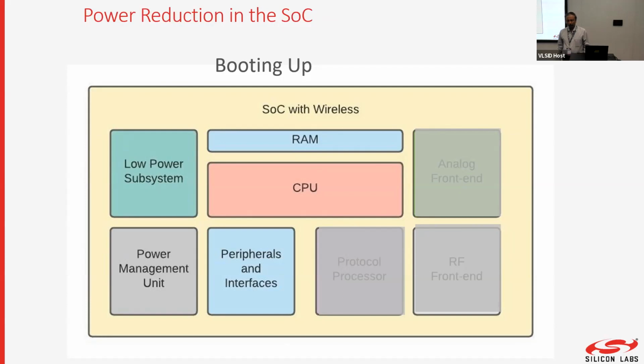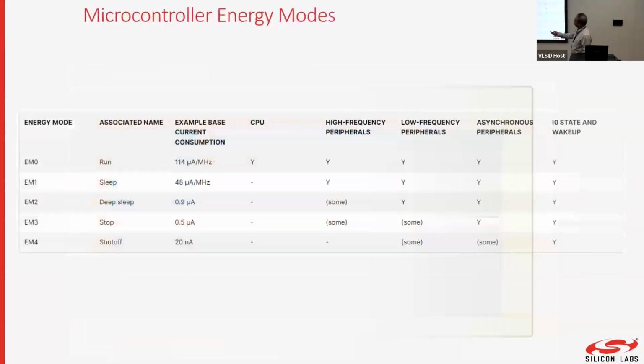If you are running the CPU at say 25 megahertz, it may use say 1.2 volts. If you're running it at 250 megahertz, it might use 1.8 volts. As a programmer, you may not know, but those will be there. And that is how you get these figures as microamps per megahertz and so on.